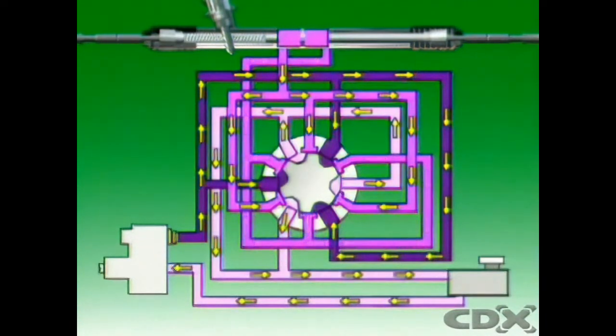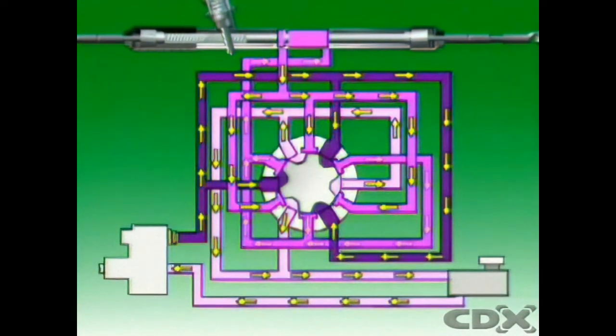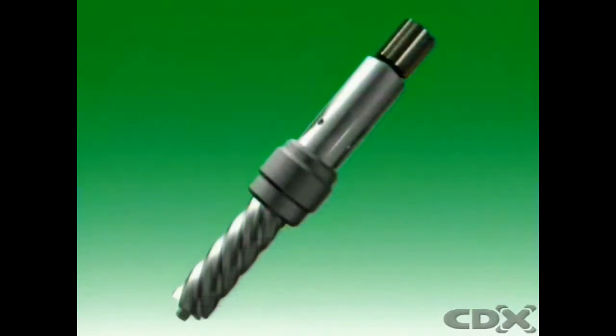No power assistance is needed. When the steering is turned, fluid is restricted from making a free return to the reservoir. It is now directed to the side that matches the turning action. At the same time, fluid on the opposite side is directed to the return circuit, back to the reservoir. Slight rotation of the valve gives a small amount of assistance, which becomes progressively greater as the torsion bar flexes and more assistance is needed. The grooves of the inner member are precisely shaped to meter the flow of fluid.